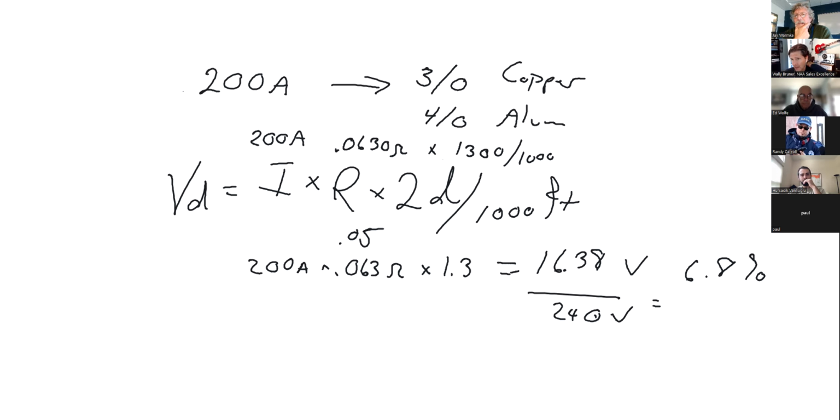And what that would affect, Ed, is what's the voltage coming into the service panel, into the main? Because they're already going to be wiring it from the transformer to the main disconnect. But if it's got voltage drop, and so your power is coming in not at 240, but something less than 240, that's what I was thinking. Yeah, then that could make the problem even greater.